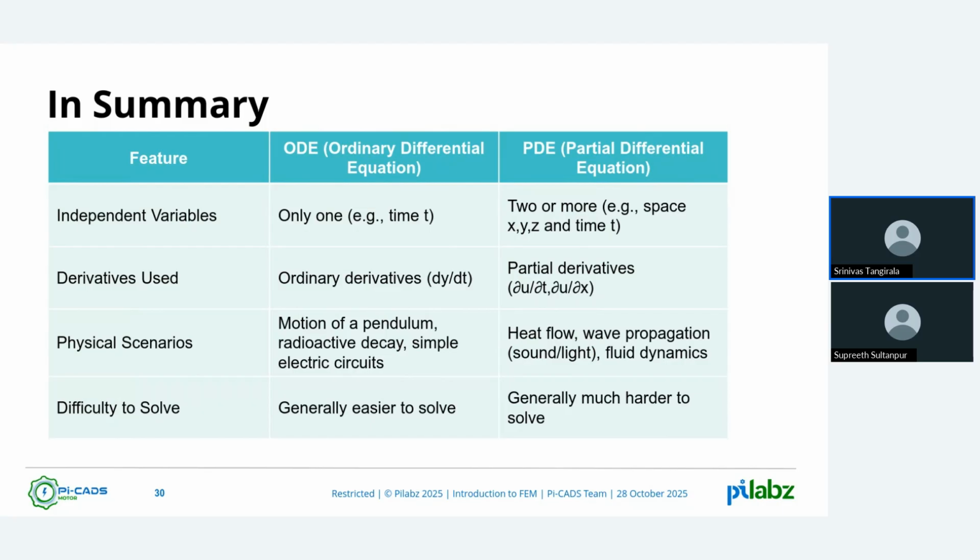A simulation will help you design that motor for maximum efficiency, and it can also tell you what the cost will be. Simulation nowadays also tells you what the winding should be, how much copper wire you use, how much material you use. So you can calculate the cost that you will incur for a particular motor design. And if that is out of range, you can go back, change the material or the design, make it smaller or bigger, and play with it, so that you get the ideal motor that you want for an application, or a vehicle, or a grinder or a fan or whatever. So that is the purpose of simulation.